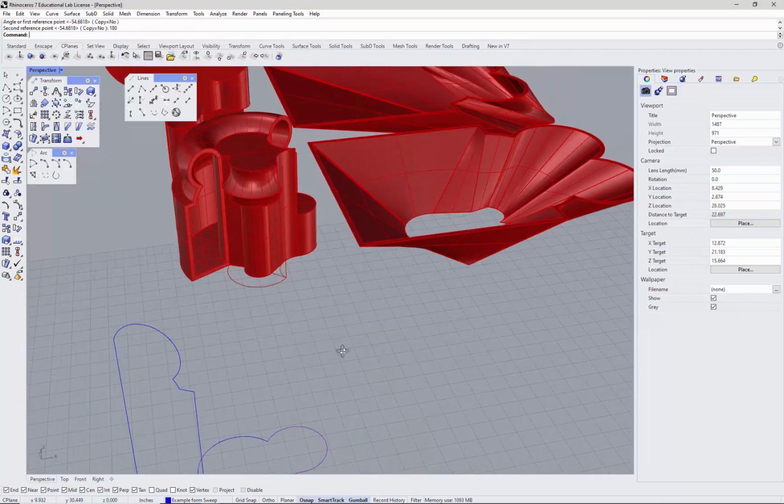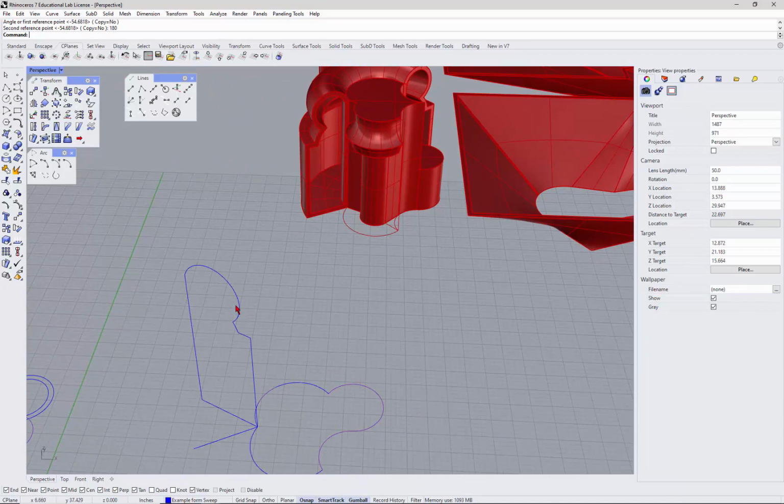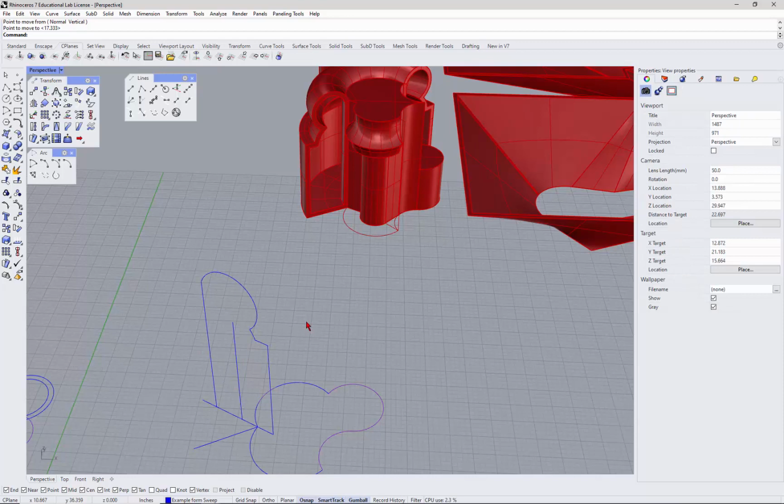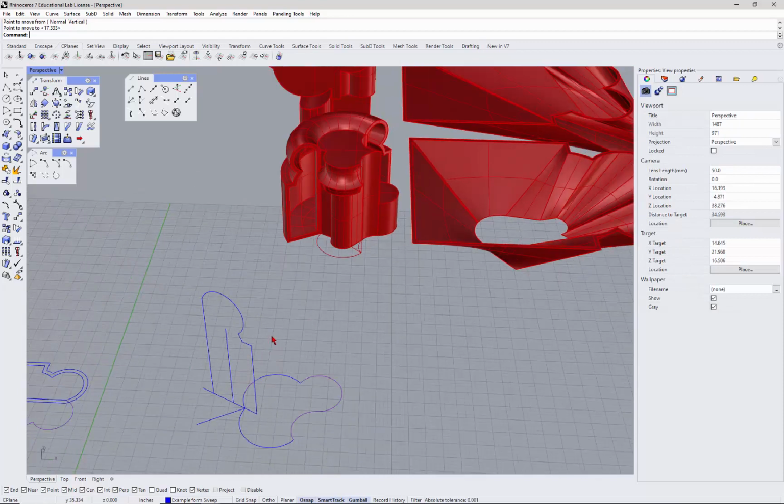And this is the extrusion, it's going straight up, and we want to push this into the extrusion, so I'm just going to draw a line from here down to there, and I'm going to move this profile in from there to there, so when I sweep it, it will give me a good negative cut out of that thing.